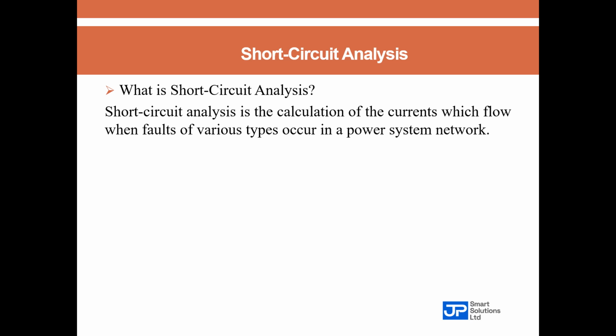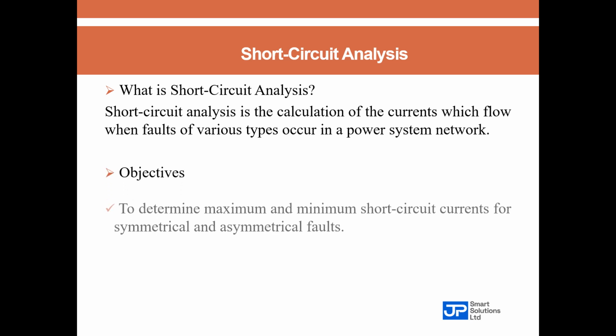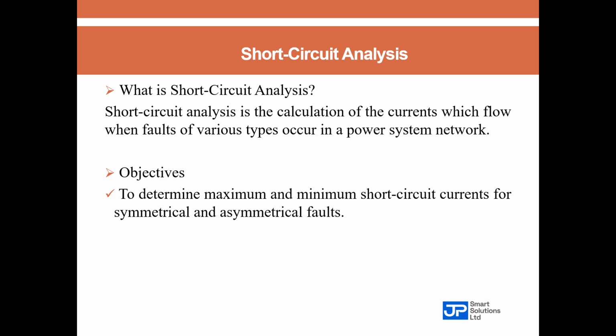So what are the objectives of carrying out a short circuit analysis? Objective number one, we carry out a short circuit analysis to determine the maximum and minimum short circuit current for symmetrical and asymmetrical faults. Remember, we said symmetrical faults are faults involving all three phases of our power system. Asymmetrical faults do not involve all three phases. So short circuit analysis will help us to know the maximum and minimum short circuit current for these faults.